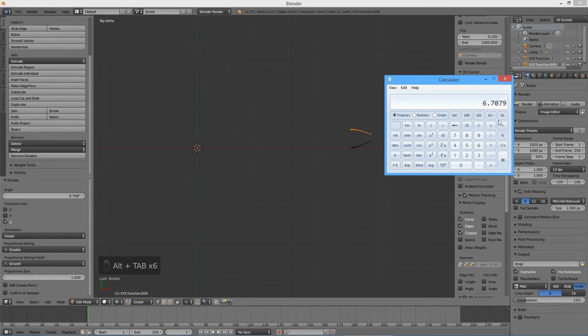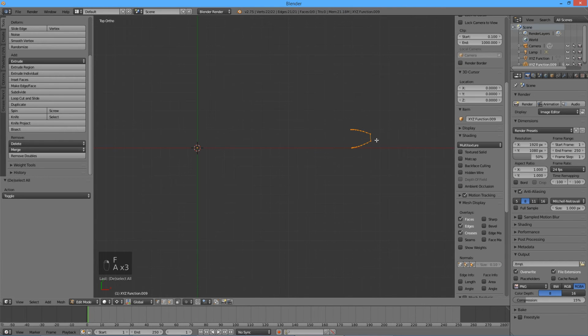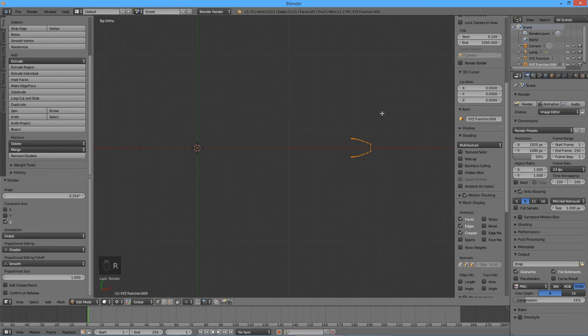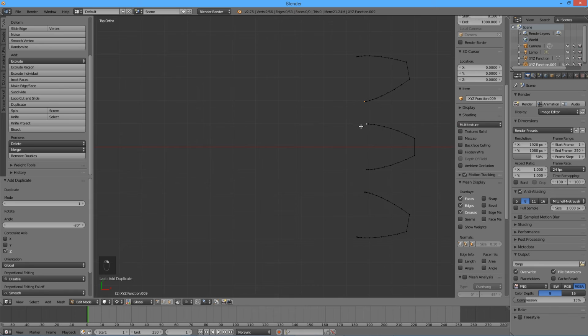Rotate in the opposite direction by half the angle used in the previous step to have the tooth straddle the x-axis. Form the tip of the tooth also. Add 2 flanking teeth by duplicating this tooth and rotating it by 10 degrees, and then duplicating it again and rotating it by -20 degrees.